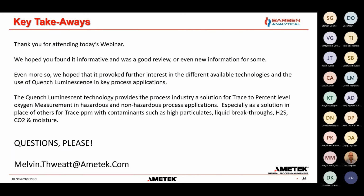Changing the sensor. We have a new question here. It says, does changing the sensor need any special configuration on the electronics? The answer is no for our standard sensors, and that covers 99% of what we do, meaning it doesn't take a configuration or anything like that. You basically take off the old cap and put on the new cap. You can punch in the factory values and be very close, but we do recommend you do a calibration at zero and span, and you'd be ready to go.